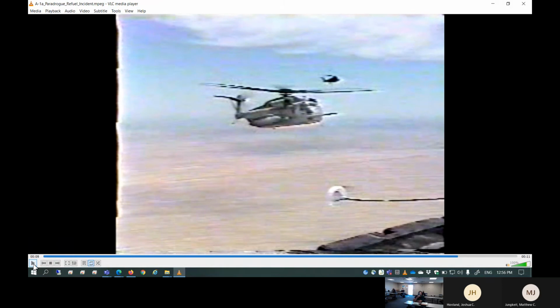This actually happens quite a bit. This is a helicopter. If a helicopter pilot is trying to be refueled with this device, this is called a paradrogue. In mid-air refueling, the pilot's tendency, if this device is unstable, goes up and down and up and down, is to try to follow through those motions. That's a basic nature of a pilot. If this paradrogue is unstable, going like this, the pilot just tries to follow that motion.